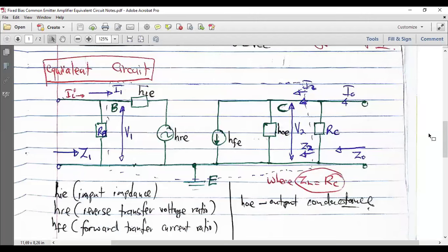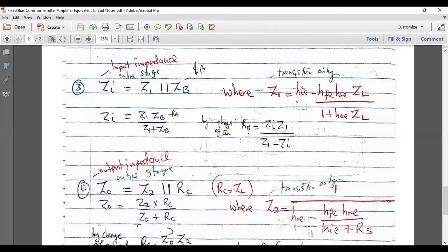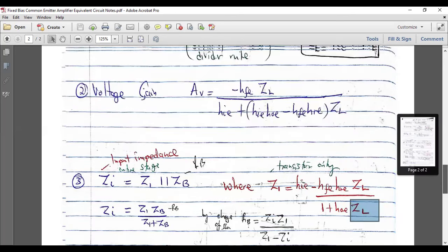If you take a closer look here, you're talking about finding RC and RB from those input and output values. In our calculations, we have to consider the first part, you need to calculate RB. But from there, you must have Z1, and Z1 has to be considered from ZL. Remember, ZL represents RC.